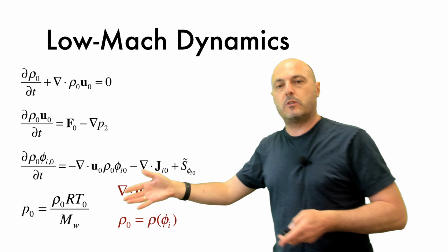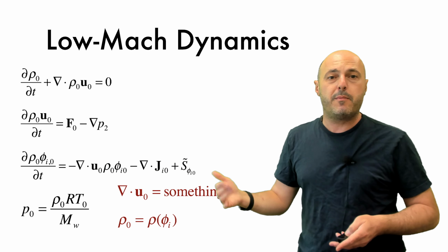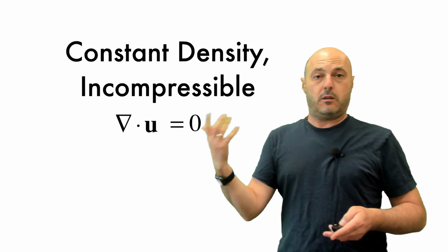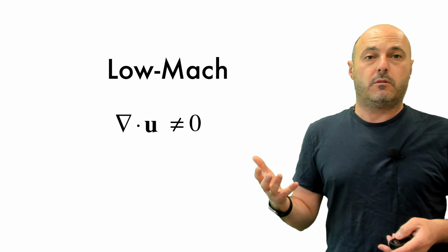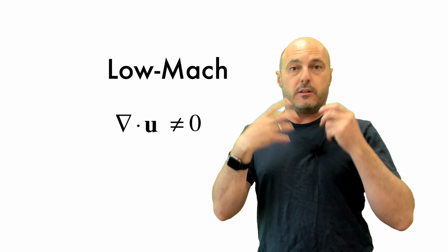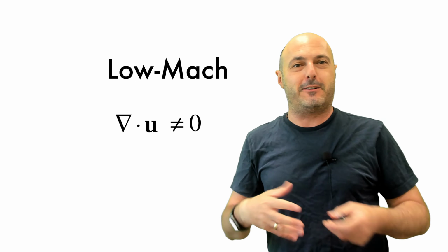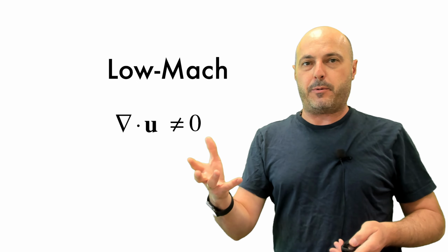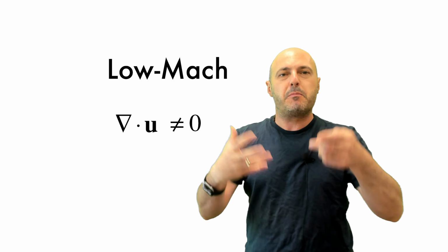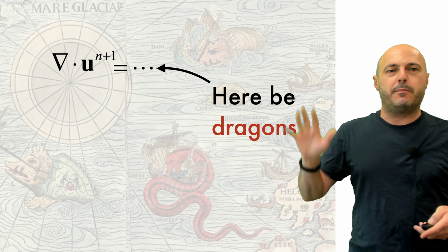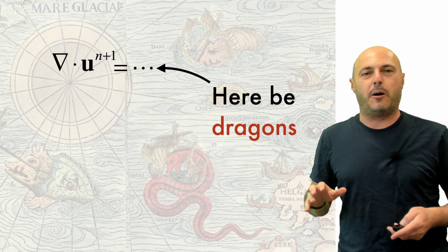Then you take these equations, you do the traditional projection to solve them. However, now your dilatation is no longer 0, because for variable density flow, div u is not 0. There's volumetric change. We're still changing the density. Remember, there's reactions going on. It's a fire. There's a supernova. There's density changes, except those density changes are not caused by the pressure. They're caused by energy release and species and things mixing with each other. Okay, so how do we crack this problem? It took us a few years to figure this out.